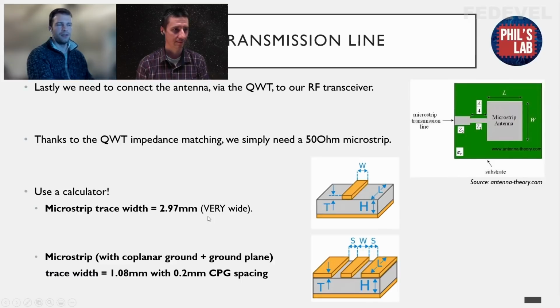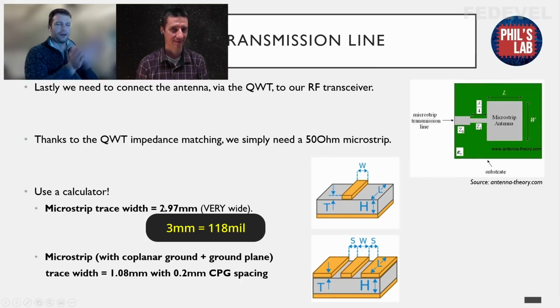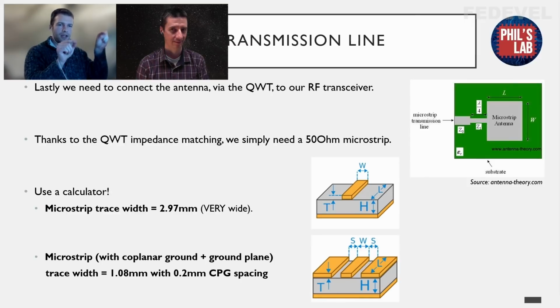So yeah, you can use the 3 millimeters if you have different components, but from a QFN, it's a huge branch out. I guess you can do it if your distance is very short. If you do a very quick increase over a short distance, we have a wavelength on the order of 20-ish millimeters, if not more. We can get away with it if we just do that expansion over a couple of millimeters. But still, it doesn't look very pretty if it's 3 millimeters. You still may need to connect the neighbor pins somehow. Exactly, that as well. And that, as we'll see later in the design, is a bit of a headache, trying to squeeze in decoupling capacitors next to a coplanar waveguide trace. So that's another thing.